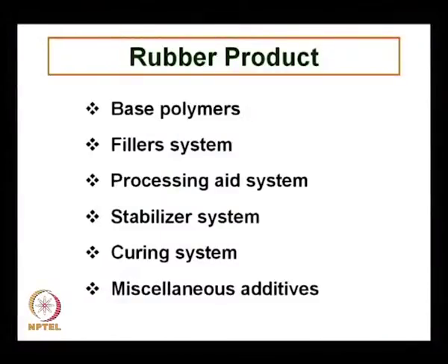Then other rubbers, say acrylic rubbers, fluorinated rubbers or fluororubbers, fluoroelastomers, silicone rubber, and other polar rubbers like thiokol rubber, which is polysulfide rubber, and Hypalon rubber, chlorosulfonated polyethylene. So, this way we can name many rubber polymers which show elastomeric characteristics, and these polymers are